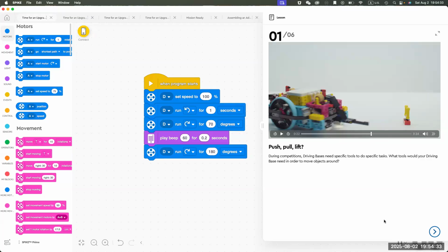So first you lower the lift down, you move forward, you use the distance sensor to get very close. Now you move a little bit more to penetrate, right? And then you lift the arm and then you drive back. Does that make sense? Okay, so these are the different steps we're going to implement when we complete the mission. But as you know, you already talked it out, so it's not that hard once you know how to do it.